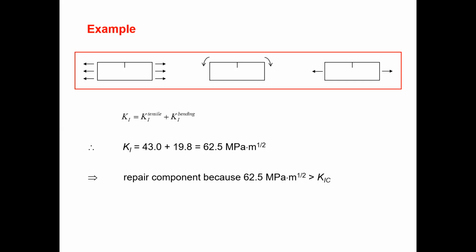Is it okay? Okay, so refill means you need to weld it or something like that. You can't fill it with some bond or something. That is not enough. It should join the two faces together. The interface should be joined. Otherwise, the effective cross-sectional area will be reduced.